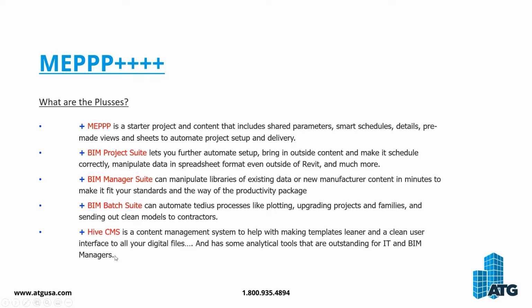So the last plus is the Hive CMS. That's our content management system. Through CTC, it basically will let you store just about any kind of a digital file. It can also store Revit families. It can store Revit native system family types like walls, stairs, doors, windows, duct styles, conduit styles, things like that that are system-based families only.